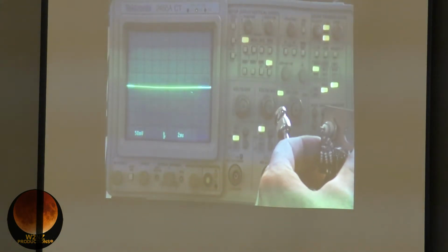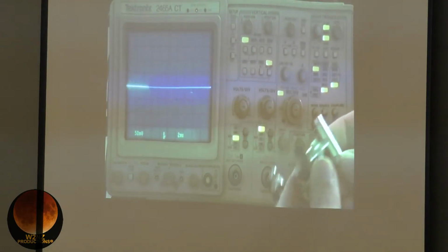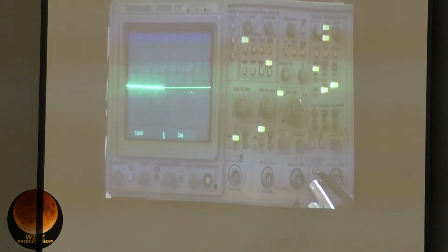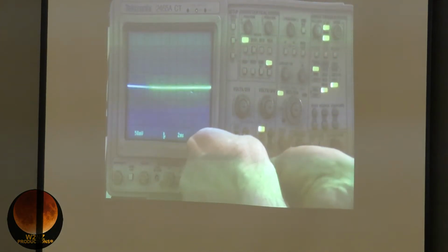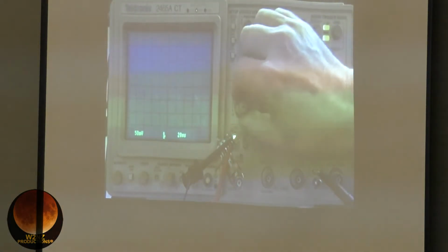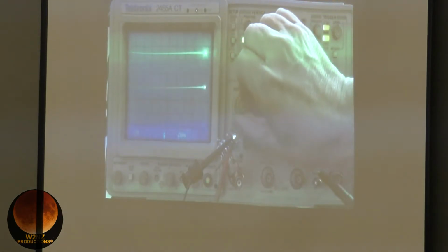So what we'll do is we'll take this signal, and I'm going to put it into a little T. And let's see, I got to find my little adapters here. There's the one I want over here. So what I'm going to do is take one end of this and connect it right up to the scope input. All right. And if we adjust the scope here, bring it down to about, there we go.